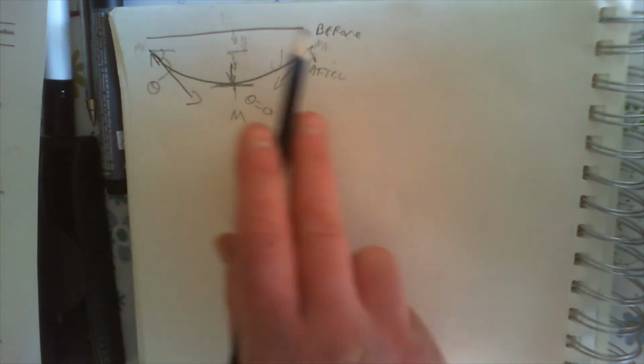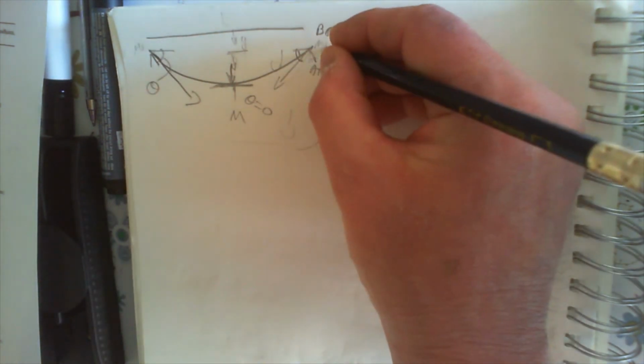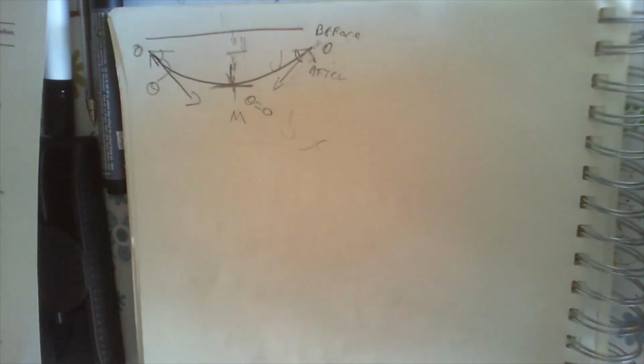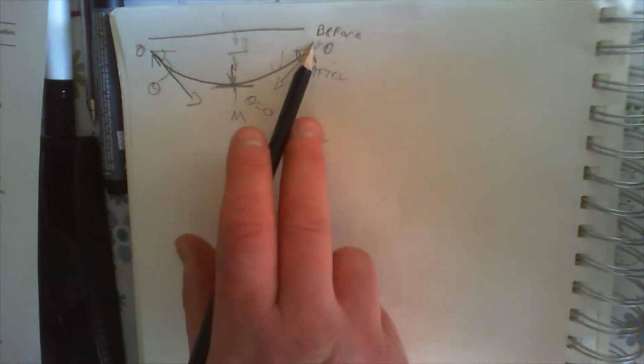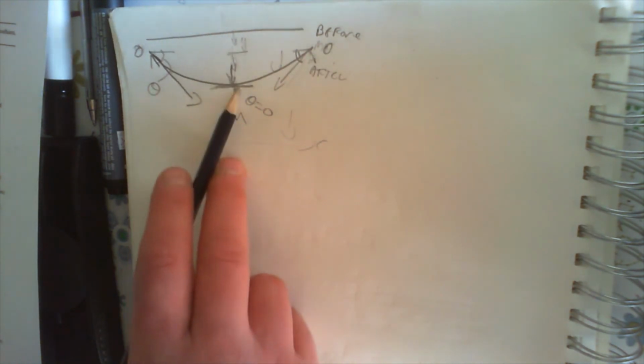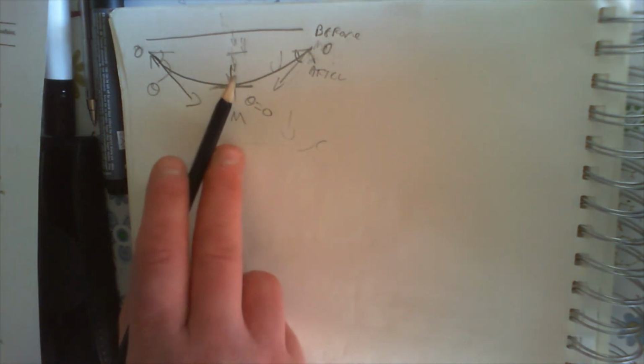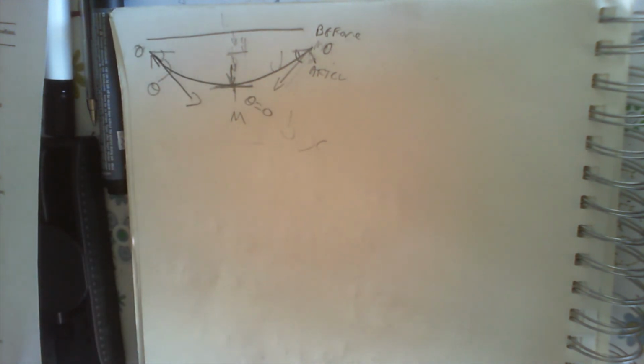But at these points on the beam, there will be 0 deflection. You can see, because obviously they don't move, do they? But this moves, and it moves a distance y, and maximum there, 0, 0. And this is handy because you can use that when you're using Macaulay's method to work out the equation of bending and slope and deflection for the beam you're looking at.